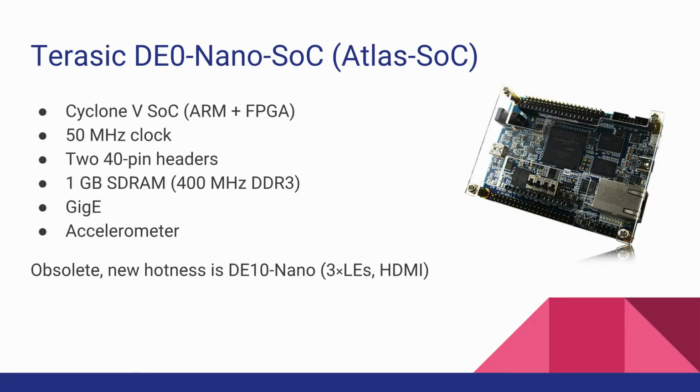So what is this dev board? There are a bunch of different FPGA manufacturers. The 2 big ones: Xilinx has about 55% of the market, and Altera has about 35% of the market. Lattice is the small one, and it has very low-end stuff. Lattice also has open source tools. Well, they don't have it, but people have figured out the binary format of Lattice, so you can get open source tools for it. So people who are into open source stuff tend to go for Lattice. And all the low-end stuff that I was talking about, like $20 boards, tend to be Lattice boards.